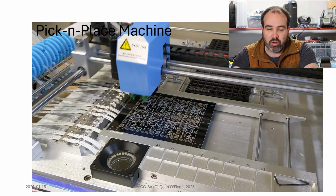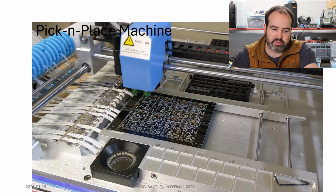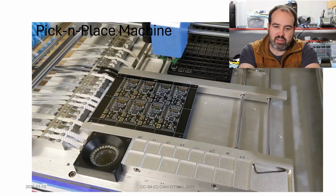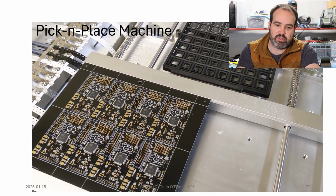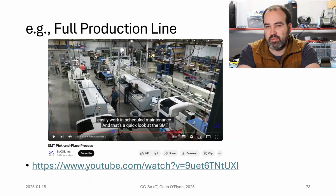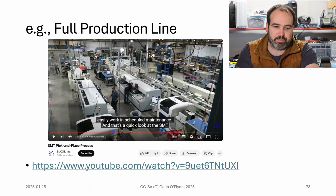What you're also doing is you need to specify data for a pick and place machine. This is a small little desktop pick and place we're using for small runs and things like that. You can see it's just picking up each part and placing it down on the board. So what we need to do is tell this machine where each part goes. A bigger production line would look something like this. This was from Z-Axis Inc. You can check out the link if you want to get an idea of what's included. But this is a more normal size production line. You have these very big machines that would be running your boards.